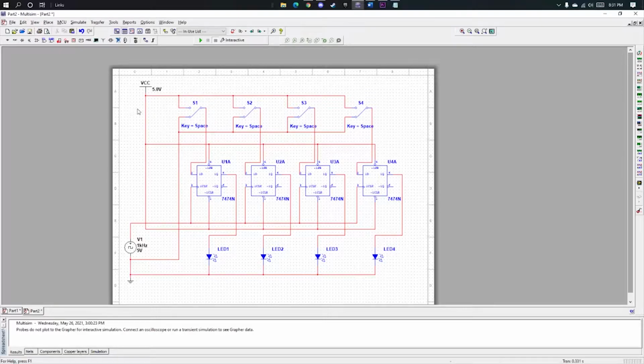Here it shows the parallel input and parallel output. For parallel in data, the number of clock pulses needed is equal to 1, and for the parallel out data, the number of clock pulses needed is equal to 0.